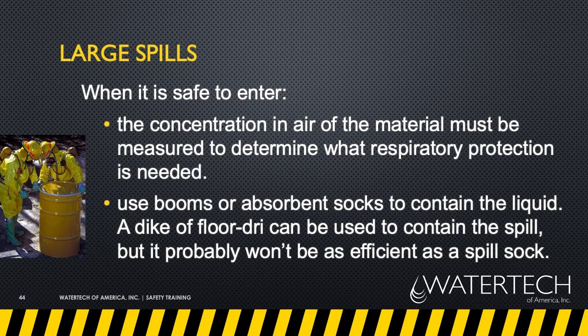If you spill, use booms or absorbent socks for cleanup. Refer to your spill standard operating procedures. And remember, if it's flammable, it must be disposed of in a specific flammable approved container.